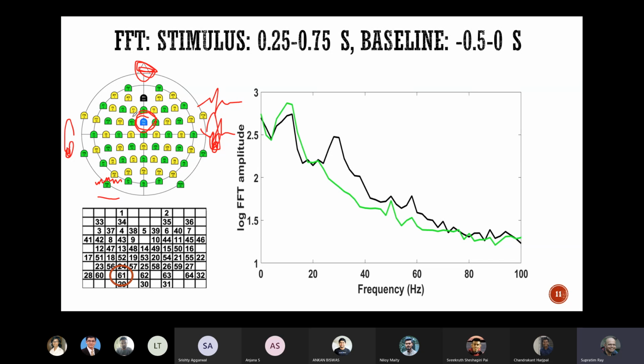You want the reference electrode to also have more or less the same noise so that they get subtracted out. So the farther it goes, if you put it on the leg, for example, it's going to catch different noise than what you have here. And then the subtraction won't eliminate the noise as much. So that's why you want the reference to be as close as possible.